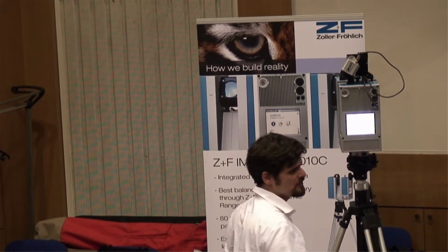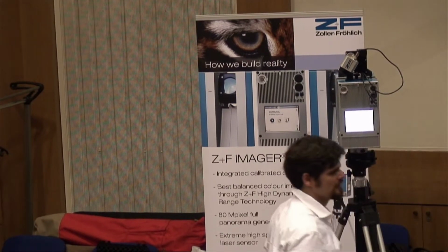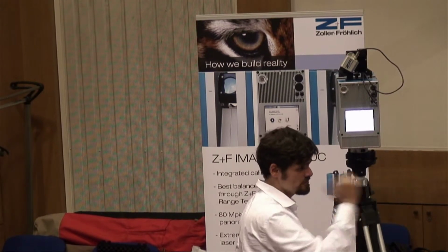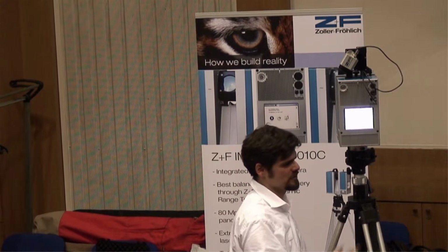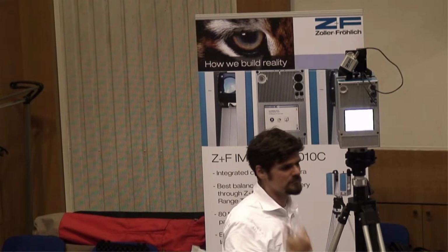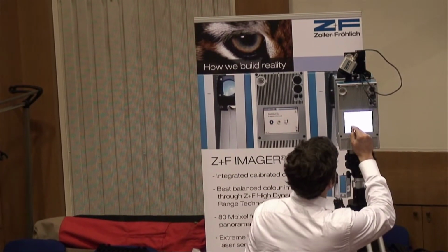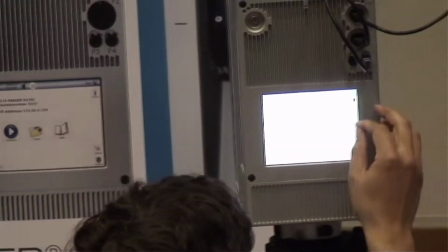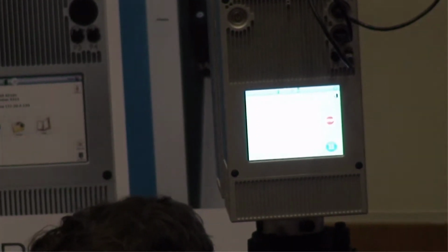Unless, for example, you go into a small corner, let's say your next position is under that table there. You don't need 6 millimeters over 10 meters, which means at 1 meter distance it's 0.6 millimeters resolution. You don't need that under the table. So there you would change the resolution and end up with a much, much quicker scan. Okay, I'll go to high and low quality now. That's a 1:40 scan. And just press the button for scanning. That's it.